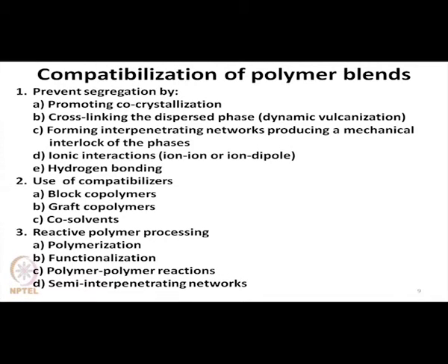If the polymer molecules are required to be crystallized in the product, that means molecularly aligned to develop long range molecular order, then the cooling rate is properly adjusted so that polymer molecules crystallize. That is the phenomenon of crystallization during cooling of the product within the mold.